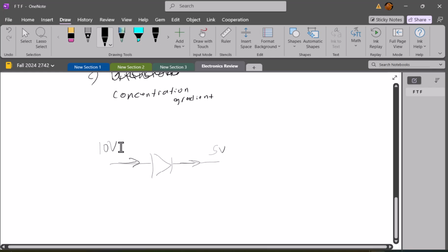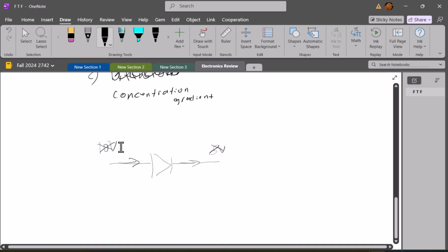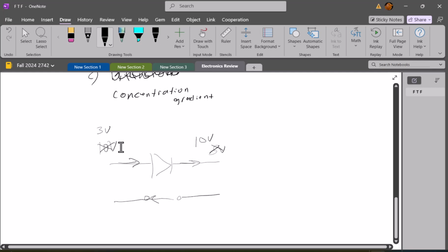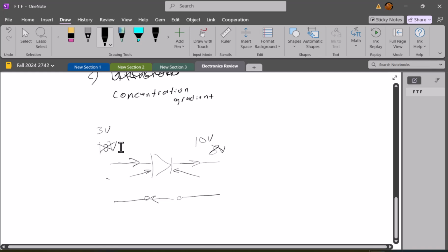And depending on what model you're using, you might or might not talk about the resistance or voltage of the diode itself. If I had a higher voltage on this side than on this side, then it's not supposed to flow, and I'm supposed to have an open circuit. But if I make that voltage difference big enough, then you'll have breakdown and current will flow. So that's what breakdown is: when current flows the direction opposite the way the diode is designed. And we call this side of the diode the anode, and this side is the cathode.